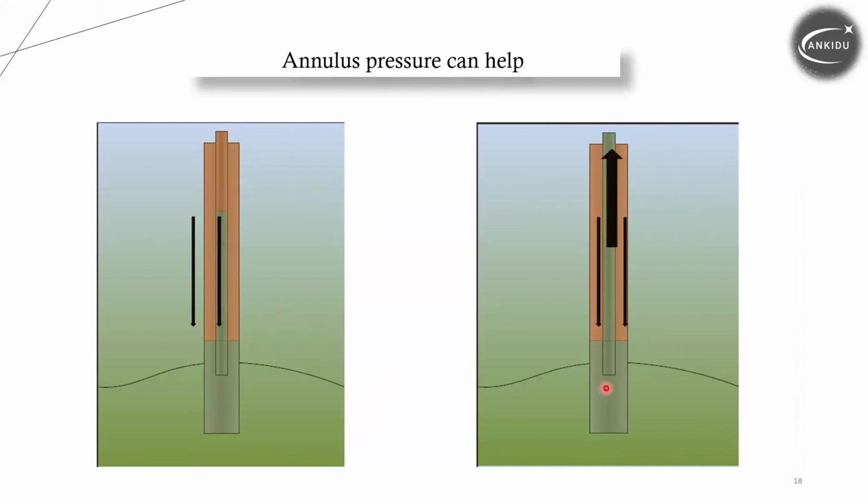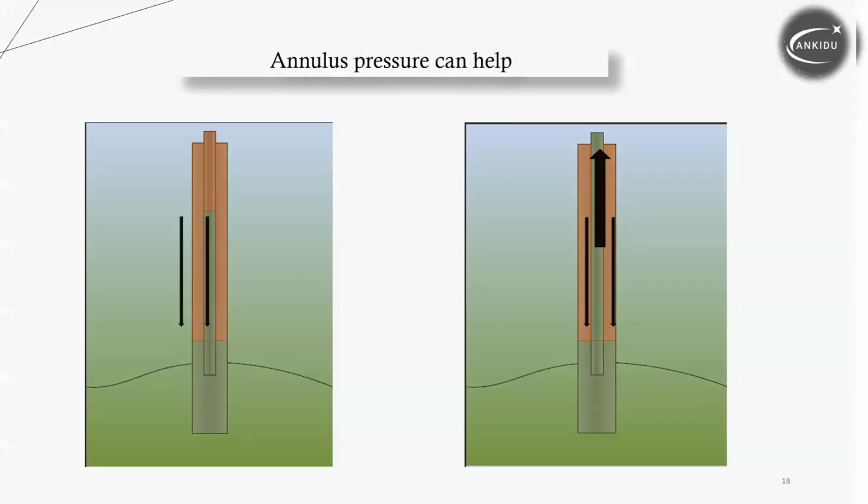One of the successful processes we found, after some attempts at unloading the well and putting those wells online again, is when we have pressure inside our annulus. This pressure can unload the well and put the well online again with natural flow without any problem, and the well is stable again, because the gas dissolves again, pushing the oil, the liquid, to the surface without any problem. So annulus pressure can help for that reason.